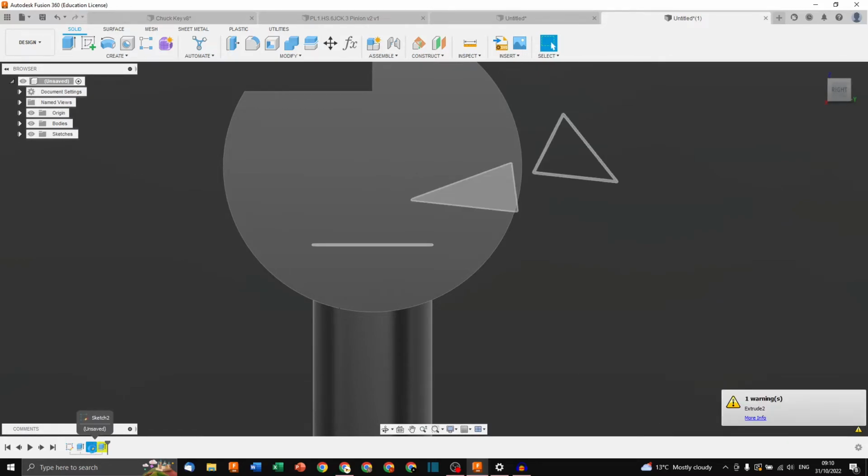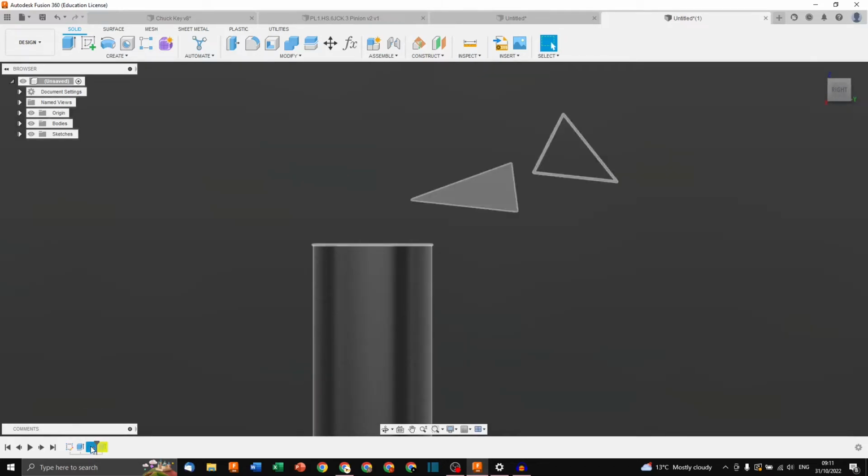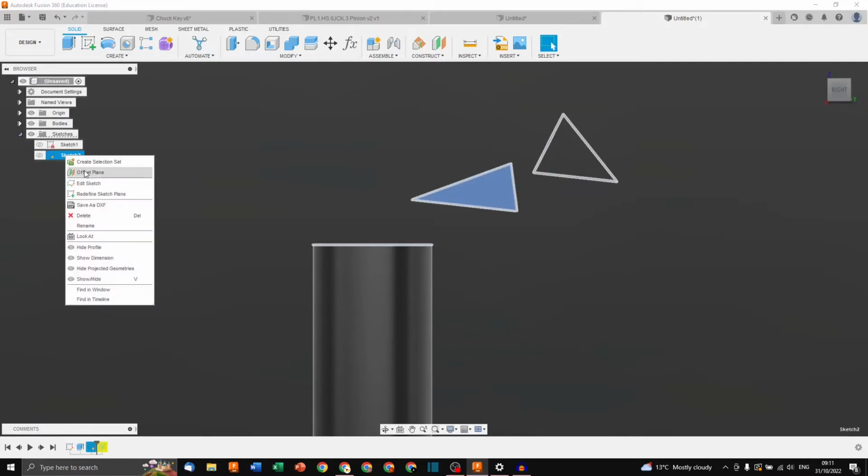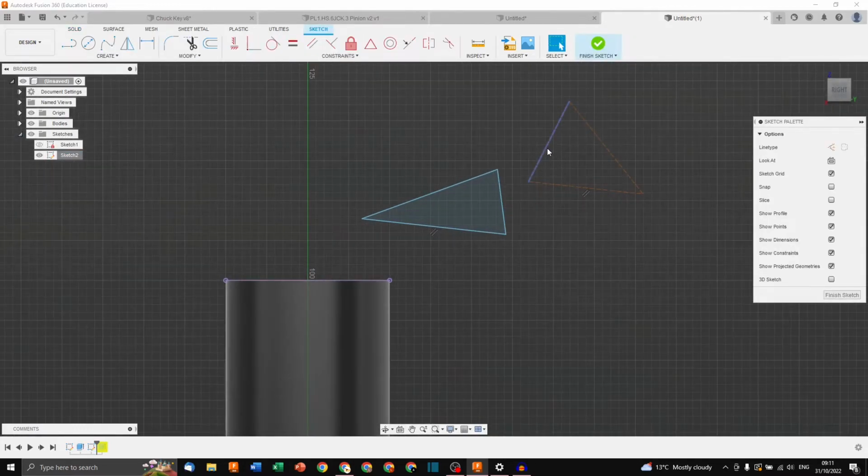So if I go back and edit my sketch, it really doesn't like it. You can see that this doesn't close. I can now click on an object that I put down already and press X, and this toggles the construction to full lines. Or I can just click on the line type. It toggles it too. And you can see when I change the last line of the triangle to a full line, then it closes the object. So you should always use construction lines for objects that you will not be extruding, but they are very useful to not clutter up your design.